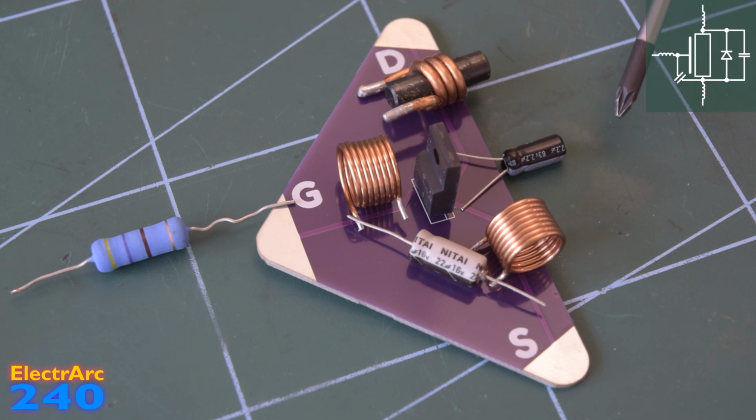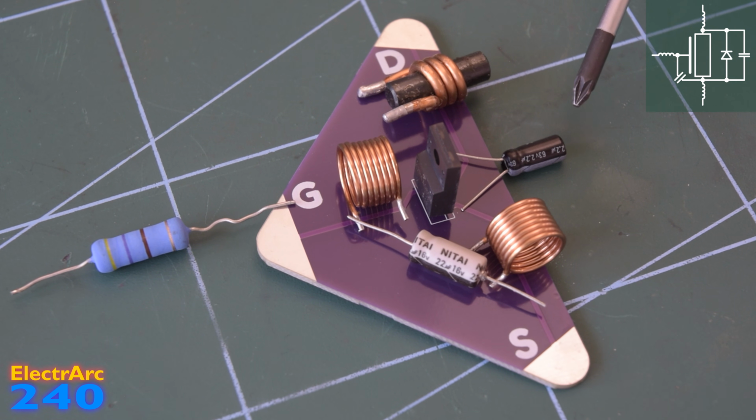This capacitance is charged up every time the MOSFET is turned off, and there's a voltage across it between the drain and the source. For example, in the half-bridge configuration of, say, an electric car inverter, I might have 400 volts across the MOSFET when it's turned off. That 400 volts has charged up our drain source capacitance. Now when we turn our MOSFET back on, there's only one place that the energy stored in this capacitance can go, and that's into the MOSFET.